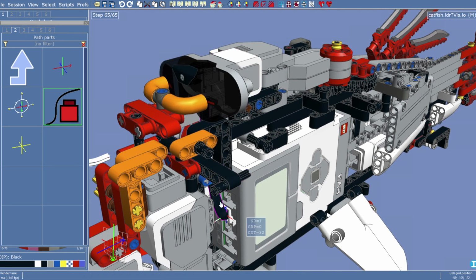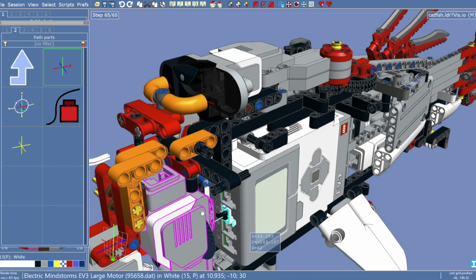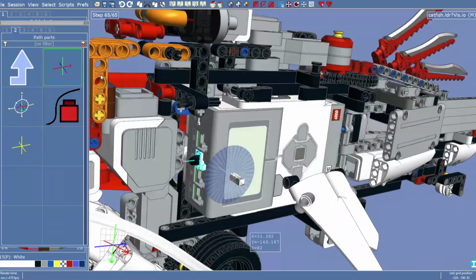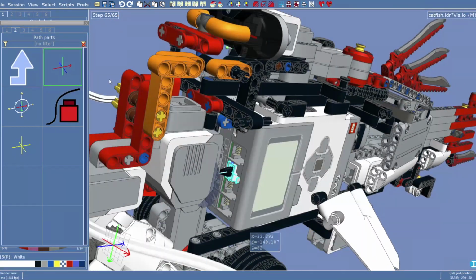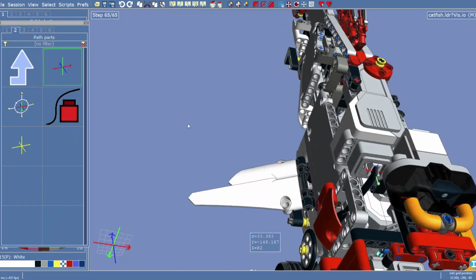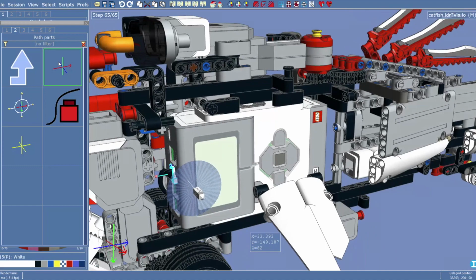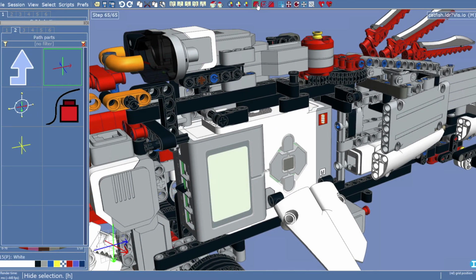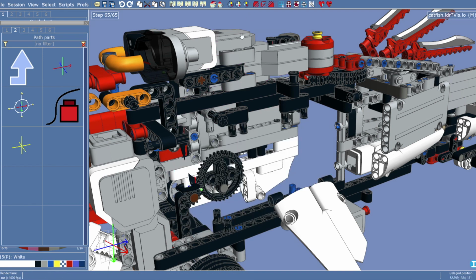So I'm still here in sub-model editing mode with N, and I can click this one, and then I can press the insert key on the keyboard, and this will insert this Path Bezier Meta. Oh, it has inserted it into an awkward place. Where did it go? That's the trouble with LDCAD. It sometimes does crazy stuff. Let's see if we can hide some more of the model and find it.